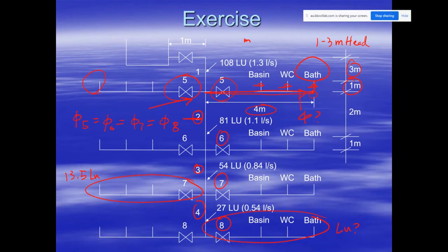So that means I can fulfill the requirement, say for the discharge pressure, maybe within my expectation. Maybe in the lower part, I can make the pipe size smaller, because in here, sufficient gain of the potential energy. Maybe we gain a lot. We use the pressure reducing valve to reduce the pressure, artificially creating some friction.